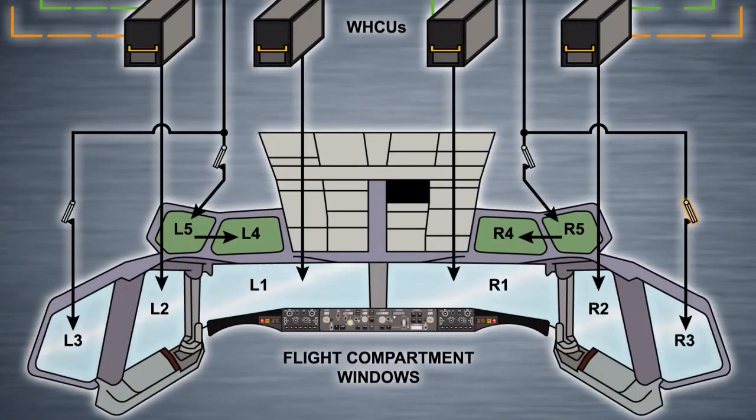The temperature of window numbers 3, 4, and 5 is maintained by 4 separate thermal switches. These thermal switches open and close to maintain the correct window temperature. The switches close to allow current to pass, and open due to thermal expansion of their corresponding windows. There is one switch attached to each number 3 window, and one switch attached to each number 5 window. Window 4 dovetails off 5, so they share the same thermal switch.